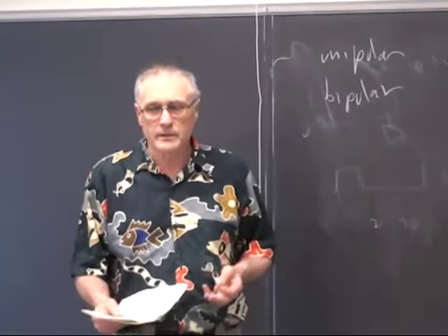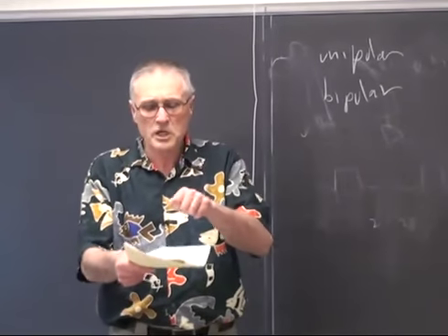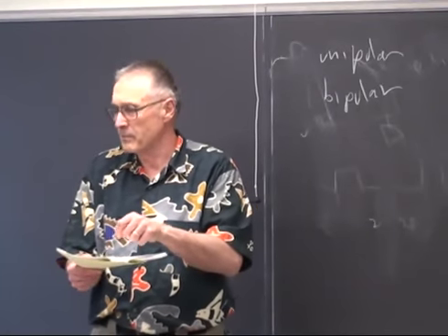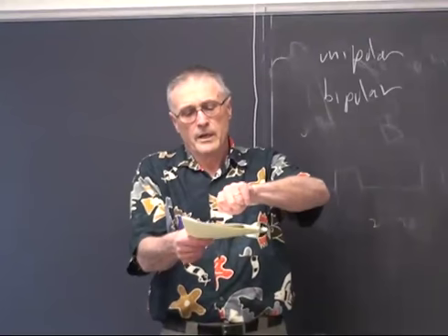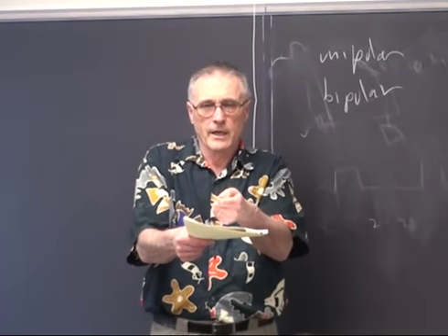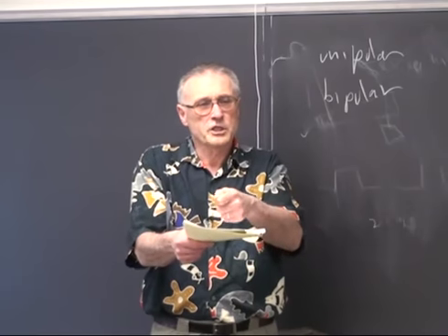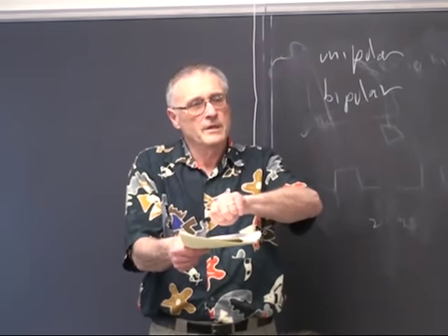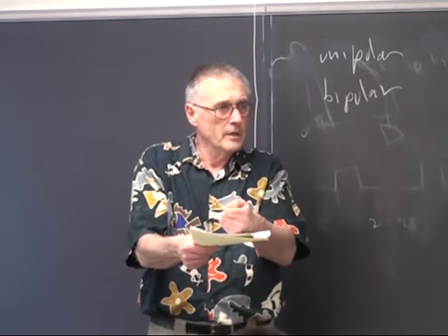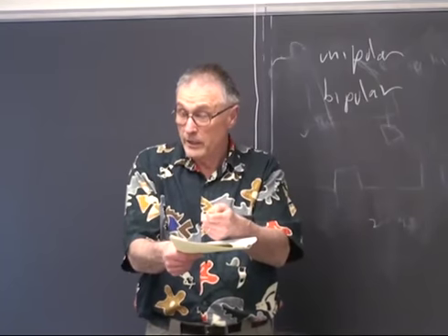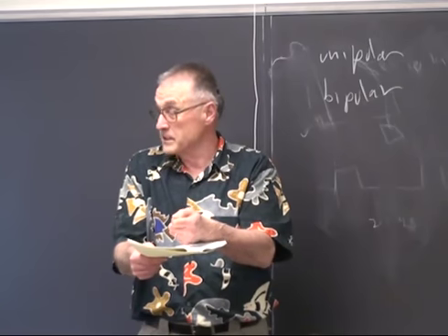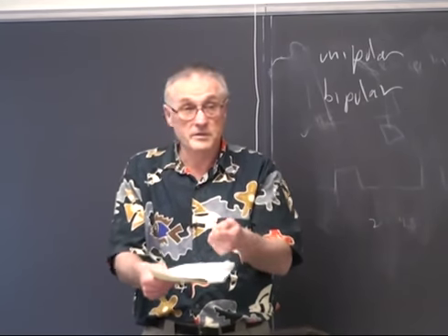Stepper motors are inherently digital. If you take the shaft of a permanent magnet stepper motor, and that's what I'm going to be talking about, and you turn it, you can feel it go click, click, click, click. Even a very cheap motor has perhaps 40 detent positions per revolution. And it will produce torque. It'll produce a holding torque at zero current, because it is a permanent magnet being attracted to soft iron.